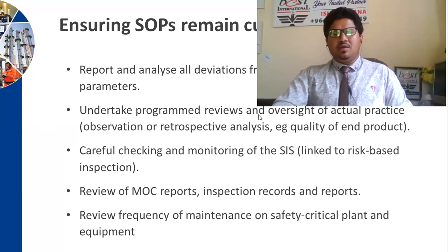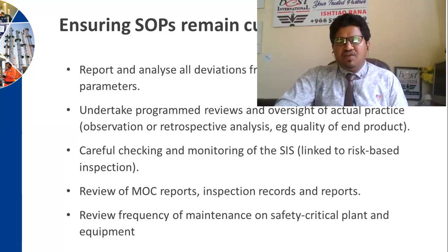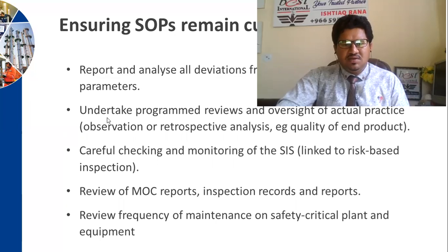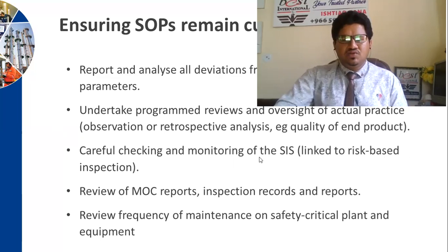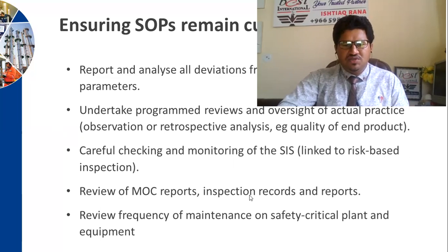Ensuring SOPs remain current and accurate: report and analyze all deviations from the expected process parameters, undertake program reviews and oversight of actual practice, observations or retrospective analysis, quality of end product, careful checking and monitoring of SIS linked to the risk-based inspection, review of MOC, management of change, inspection records and reports, and the review frequency of maintenance on safety critical plant and equipment.